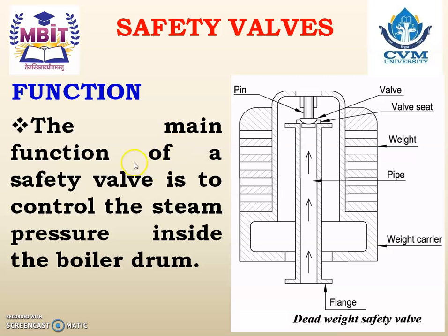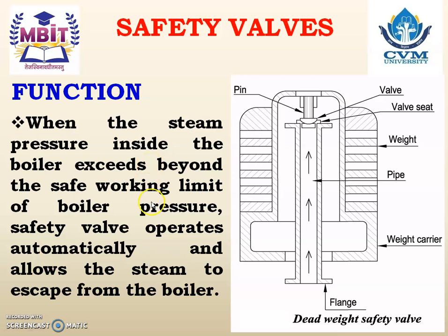Function. The main function of a safety valve is to control the steam pressure inside the boiler drum. How? Let us see. Whenever the pressure of steam inside the boiler increases beyond the safe working limit of boiler pressure, at that time safety valves operate automatically.